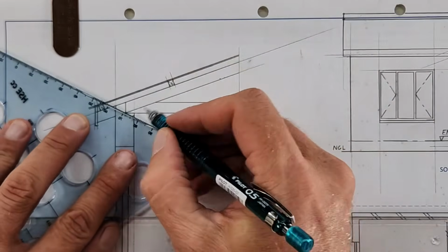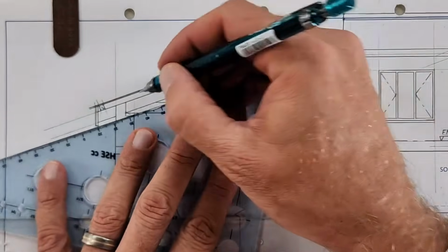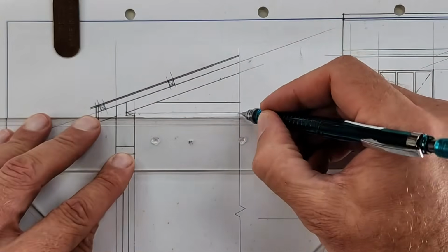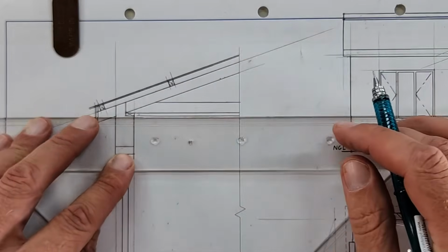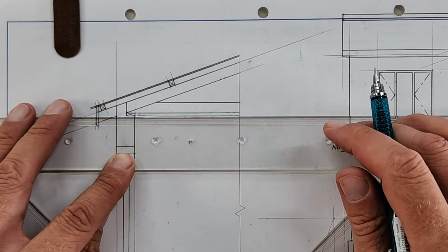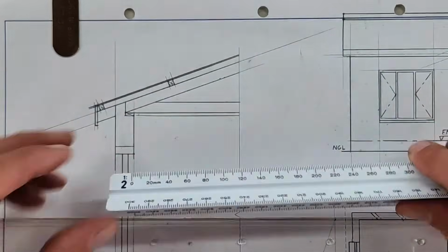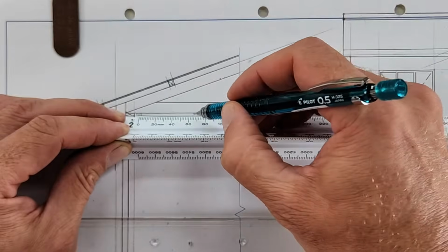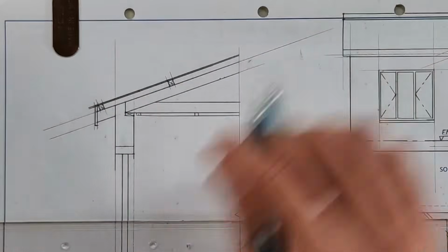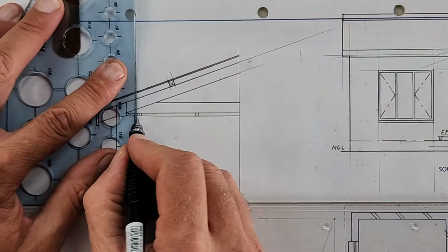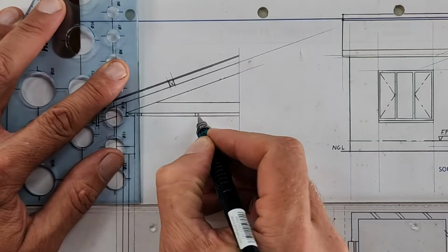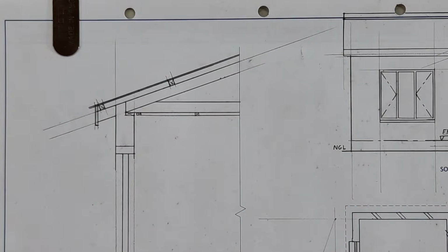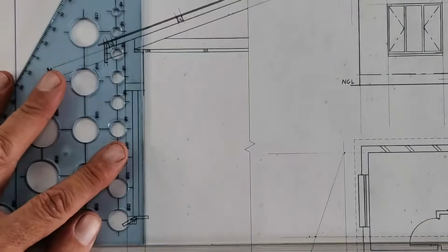Okay, do we have to put in a ceiling? We do. So that's a brandering of 38 by 38. It's going to be the same width, so I can draw my ceiling in. That's center to center. Brandering 38, 750 center to center. Okay, so there's the first one. And then at 750, there's the next one. So it's only two. First one right here in the corner, and the next one. Okay, there we have our brandering. Alright, coming down.